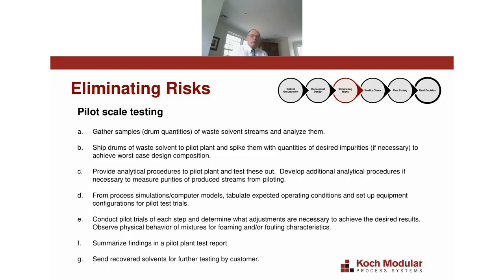Sometimes we'll see that there are other impurities in the client's feed that they did not report to us initially, and then we'll have to figure out how to deal with those other impurities. That happens fairly often. We'll also find out whether there's some gross fouling or foaming that takes place in a distillation column. The columns that we're using for the most part are glass, and so we can see into them.